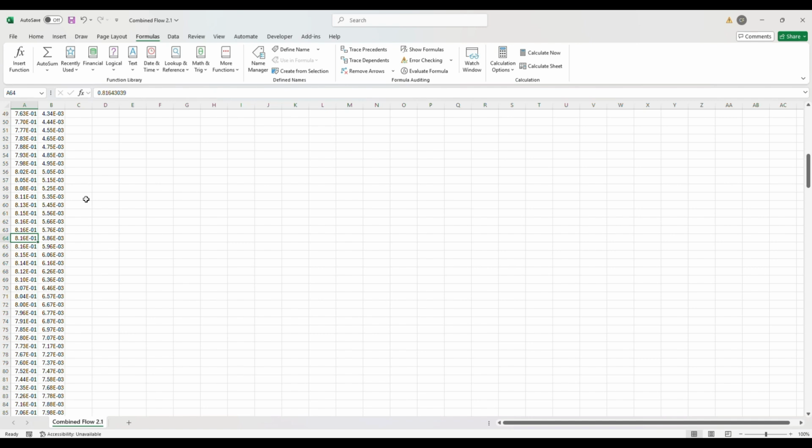And then our corresponding y location is this one, located in the formula bar. Convert that to millimeters. 5 millimeters, 5.8 millimeters. So just above our midway point, which is to be expected because our flow is not symmetrical because of the upper plate that is moving.